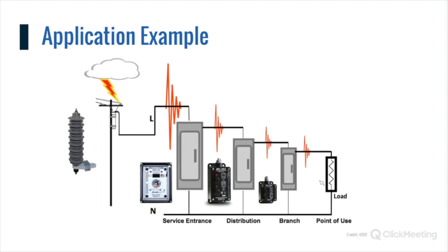And so Alan, I just wanted to reiterate that point and just to think about that for just a second here, to understand that, look, there is no simple rule here of, look, every panel gets a surge protector. That doesn't have to be done. In this simple illustration we have here, I've got a 480 volt panel to a distribution panel to a branch panel to a load. That configuration changes a lot, where it may go from 480 directly to 120. I can go 480 down to 24 volts directly. So there's a lot of things that need to be thought about, and that's the process of trying to digest all this. And so I just kind of wanted to capture that thought real quick.